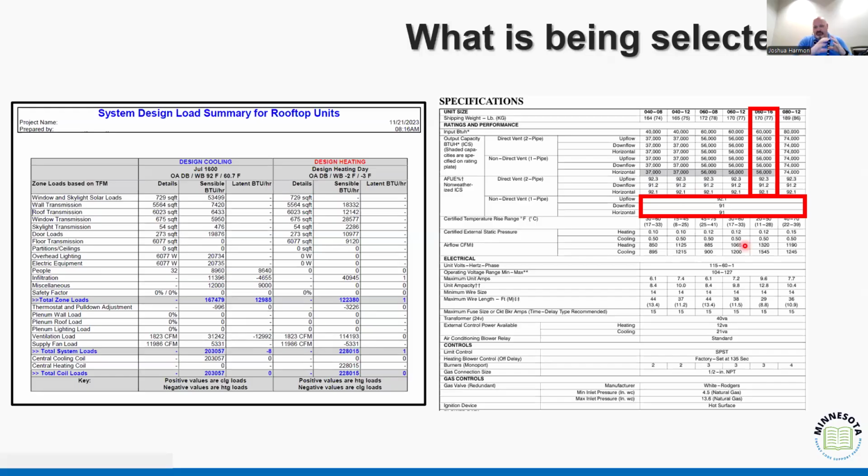So we're not doing that air modeling, that velocity monitoring to say what is hitting, how much air am I getting into this occupied space or this habitable room, right? And that's where it's important for us to calculate. Most of the rehabs I'm seeing, especially some of those change outs, all come back to airflow. Their bigger problems are airflow than they are heating and cooling loads. But because of that, we're having to size things and document that's the reason.